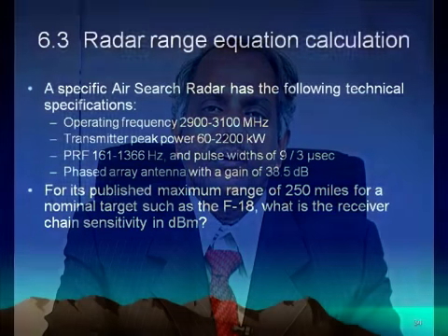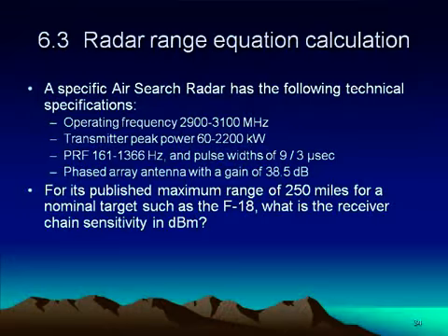That means, if you take the practical transmitter power, the practical minimum received signal strength required, the gain of the antenna, wavelength of operation and all other things, and calculate the range with this equation, that will be only the theoretical range. A thumb rule is that in practice you get only half of this value in your measurements.